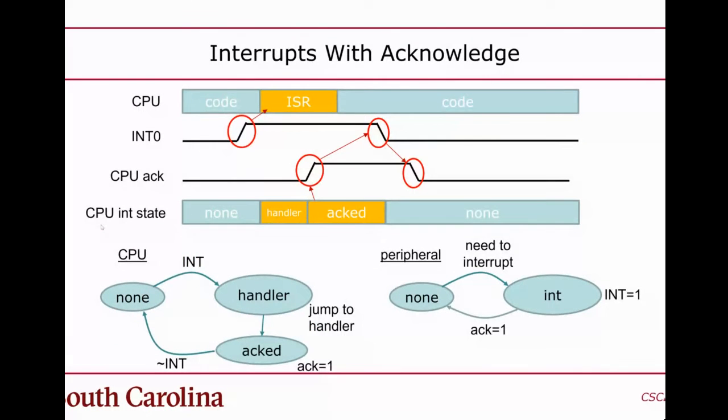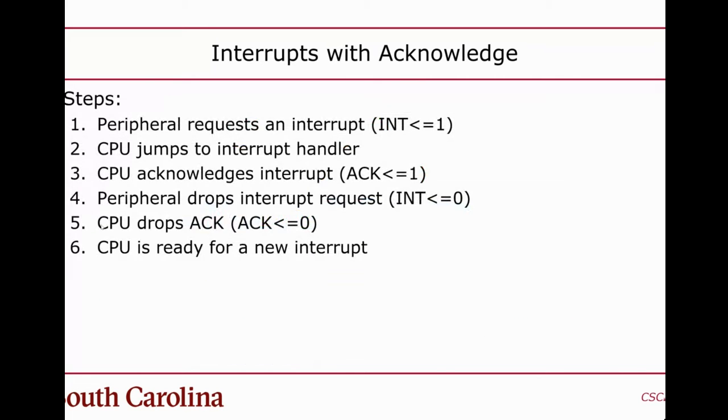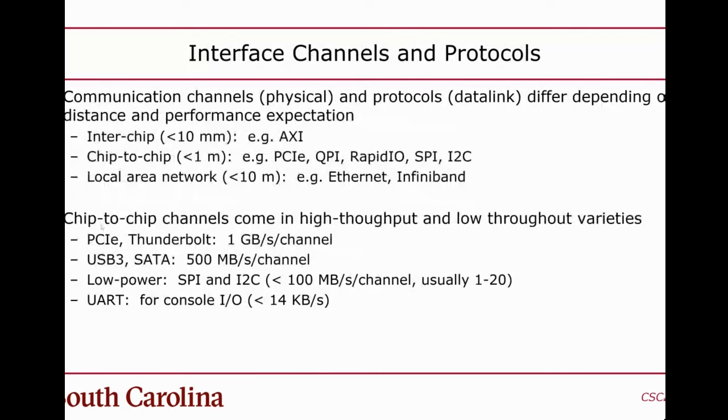But there's also, in a little bit heavier weight processors, embedded processors, an interrupt acknowledge. That's a signal that goes from the CPU back to the peripheral that allows you to create a handshaking for these interrupts. So you end up going into a sequence where the peripheral will request an interrupt, the CPU will at some point go to the interrupt handler. The time it takes to start servicing the interrupt depends on what the CPU is doing at the time of the interrupt. Sometimes it has to finish whatever it was doing. Sometimes, the CPU may already be servicing an interrupt